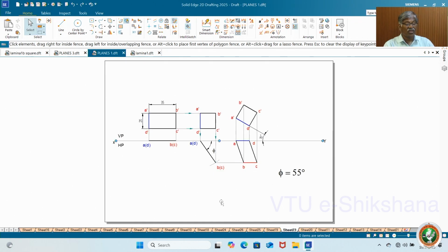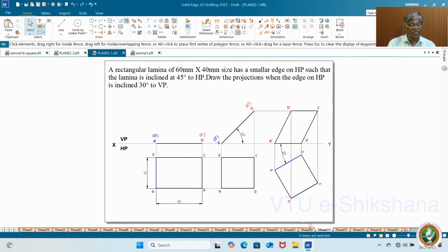So this is how you get the final figure. So I will repeat: the front view appears as a square. Now the corresponding angle you should get by taking this as a radius and drawing an arc. Then you redraw, move and rotate, then project it and get the regular problem. Now, if you take any other line, you know what happens. That also I have shown somewhere.